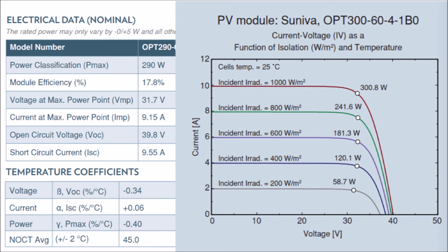Sunlight, also known as irradiance or insolation, has a linearly proportional effect on solar module power. So if the air has twice as much sunlight in it, a solar panel will produce twice as much energy, minus any temperature effects of the array or minimal amounts of energy required to start up the array.